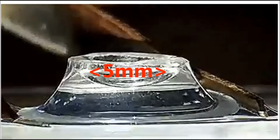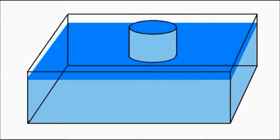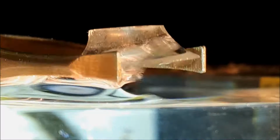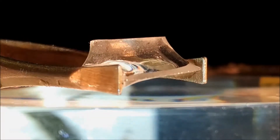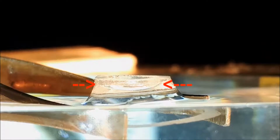As you can see, the surface inside the capillary, it's about 5 millimeter, and you can see the concave surface. And now you can see it in an animation. We have the capillary with a diameter of 5 millimeter, and when you put the capillary into the water, the water rises. It's very necessary to understand you have this concave surface because there is negative pressure inside the capillary. This is very necessary to understand, and we show you in the following some examples.